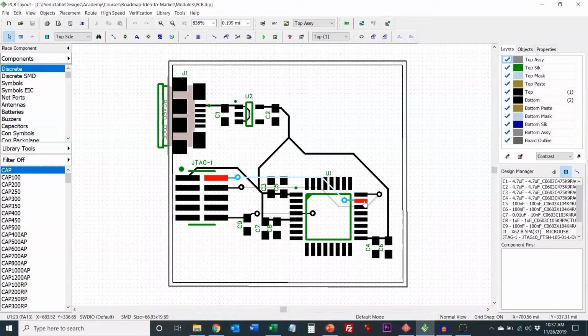But let's say you have a 4-layer board, and I need a via to connect a signal trace on layer 2 to layer 3. Well, with through vias, I can't do that. I have to draw a via that would go through all 4 layers. Even though that via goes through all 4 layers, it's only connected to layers 2 and 3. It doesn't connect to anything on layers 1 and 4, but it does exist there. It takes up space. These through vias, when you have more complex designs, can take up quite a